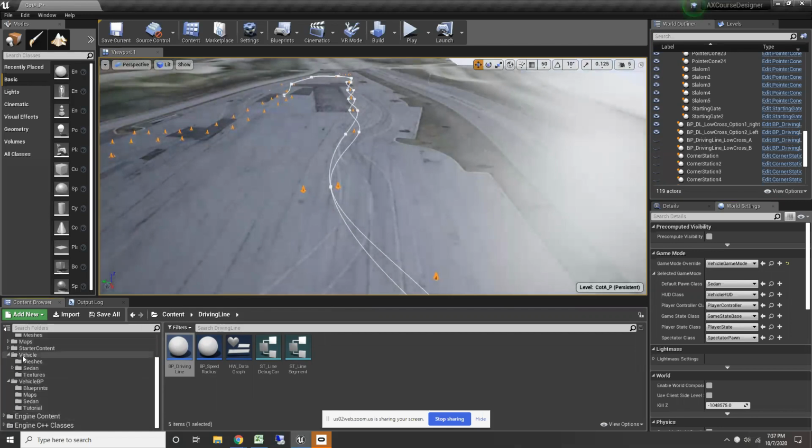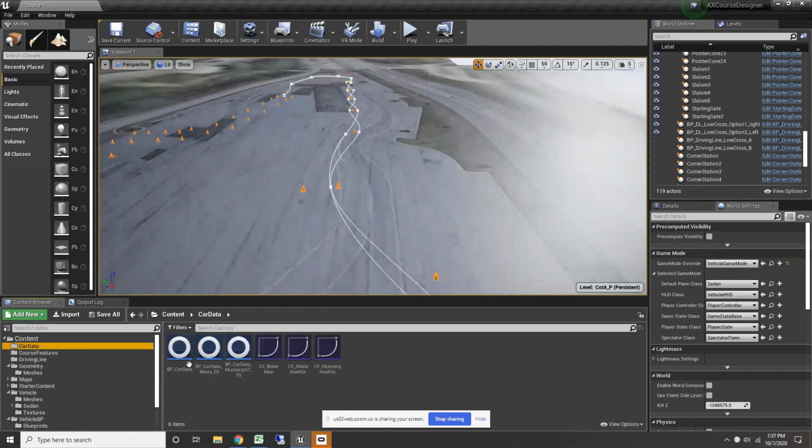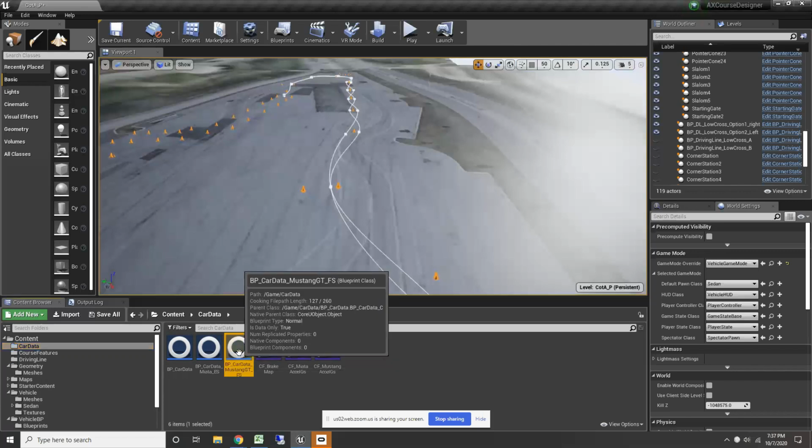I was going to say, if some of the folks have AIM Pro or something like that, data they can share with you, would that help build the model? I'll tell you what I could use. Understanding the G-forces the different cars hit, not the absolute peakest peak G you could possibly see on concrete for a 100th of a second, but just normal peak Gs would be useful.